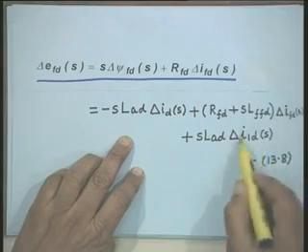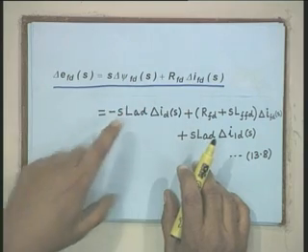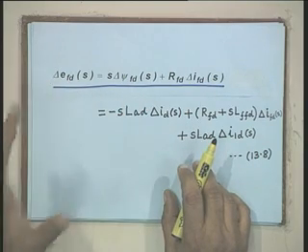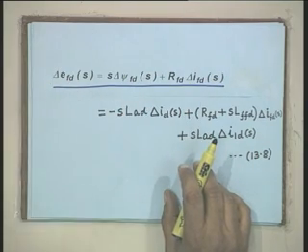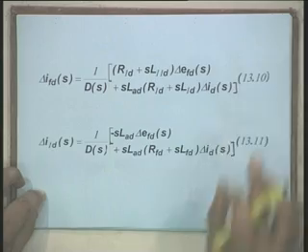We write the expression for delta IFDS and delta I1DS in terms of this quantity and these known quantities. That is, we are trying to eliminate the field current and the damper circuit current. Now, this step is a somewhat involved step, but you can obtain it.